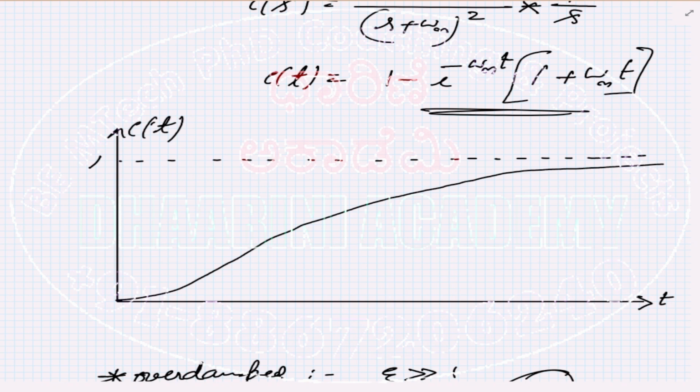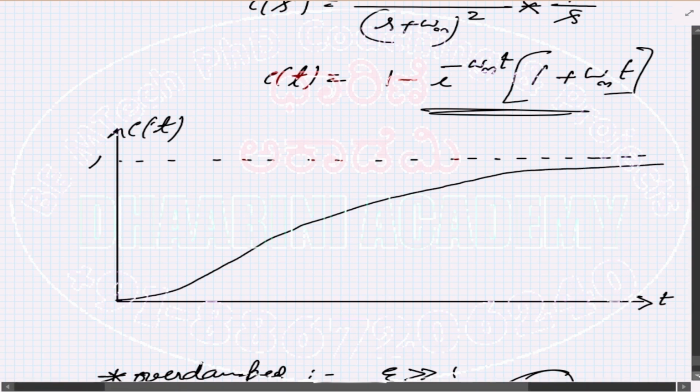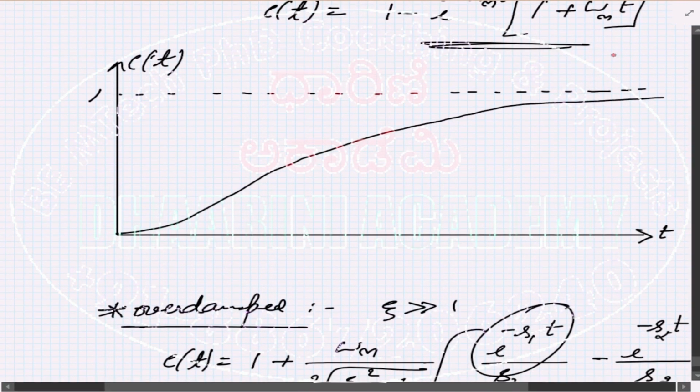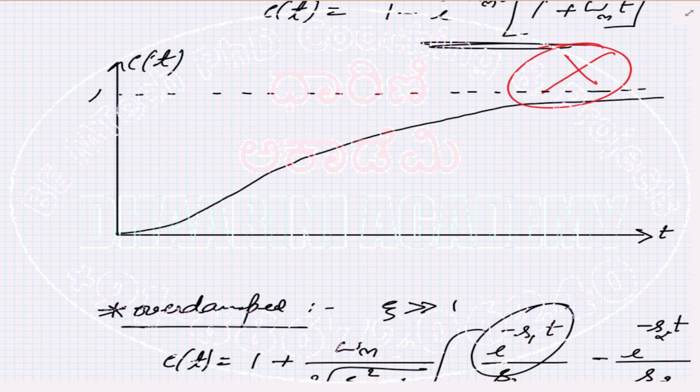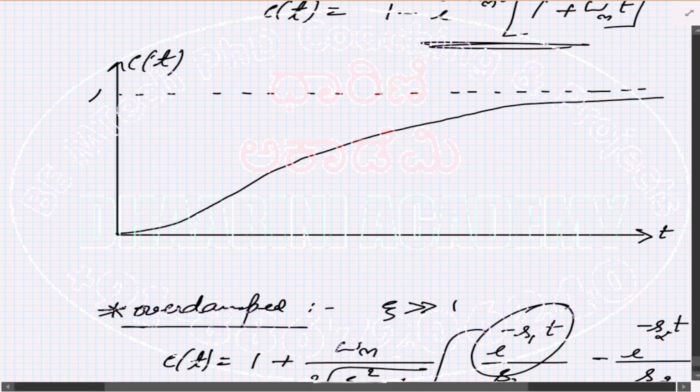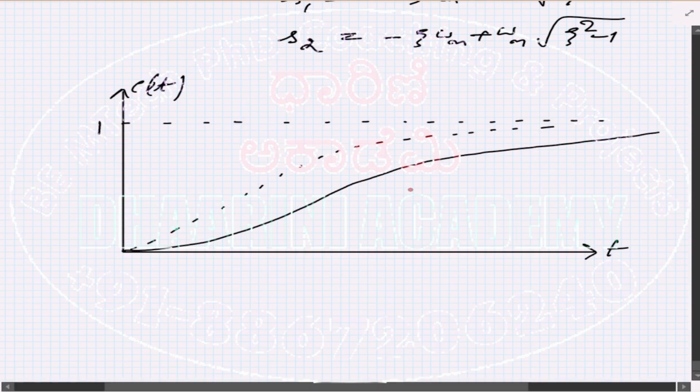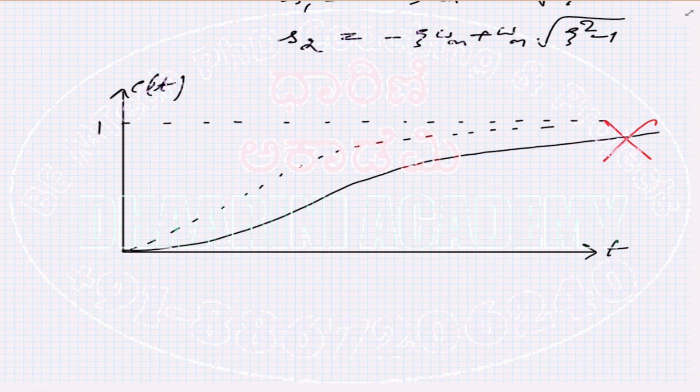Again, is it acceptable? No. So you cannot use this. That's why even the critically damped condition is not acceptable whenever we design a second order system. When that itself is not acceptable, there is no question in accepting this, right? So the over damped condition is also ruled out.